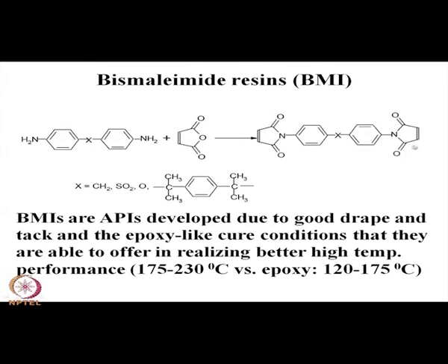And having these imide, maleic imide groups as the end groups, which are reactive. So, inside there can be this phenyl ring, flexible units, imide linkage, all these things, but at the end group there will be something reactive. So, ultimately that polymer can be curable also.